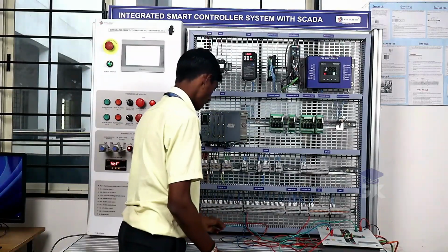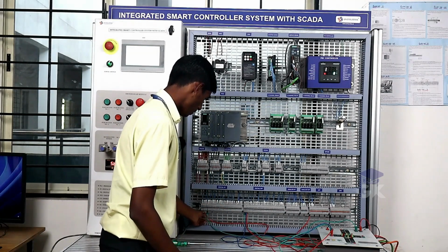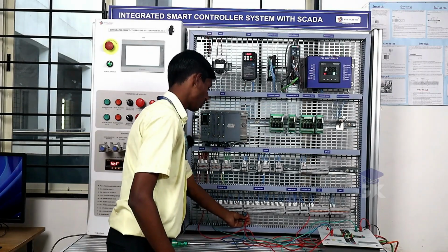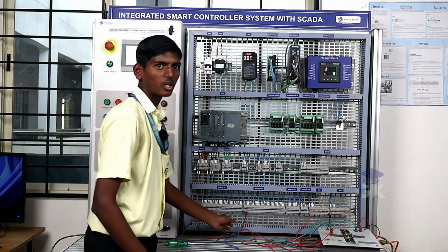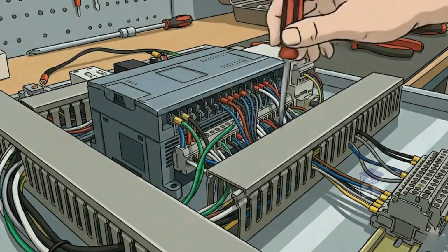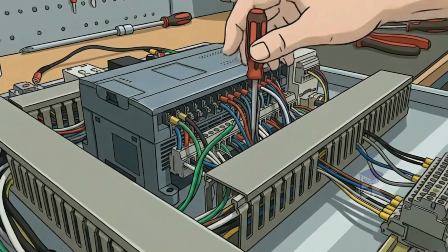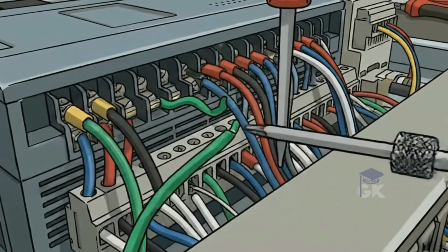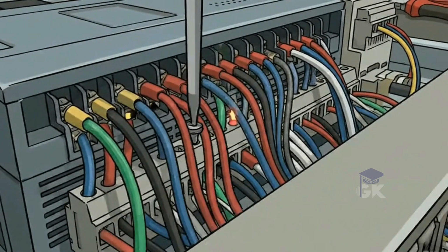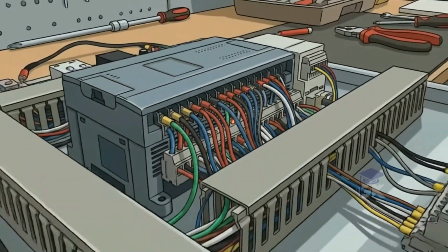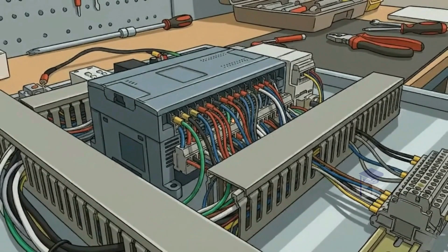So when you connect, check once or twice by grabbing patch cords that they fit or not. If it is loose, then your application won't work. Do not ignore loose connections. A loose wire isn't just a simple mistake. It introduces high contact resistance. In sensitive PLC inputs, a loose connection can cause signal bouncing, making the controller think a button is being pressed rapidly when it isn't. Always ensure a tight, secure fit to guarantee technical precision before powering on.